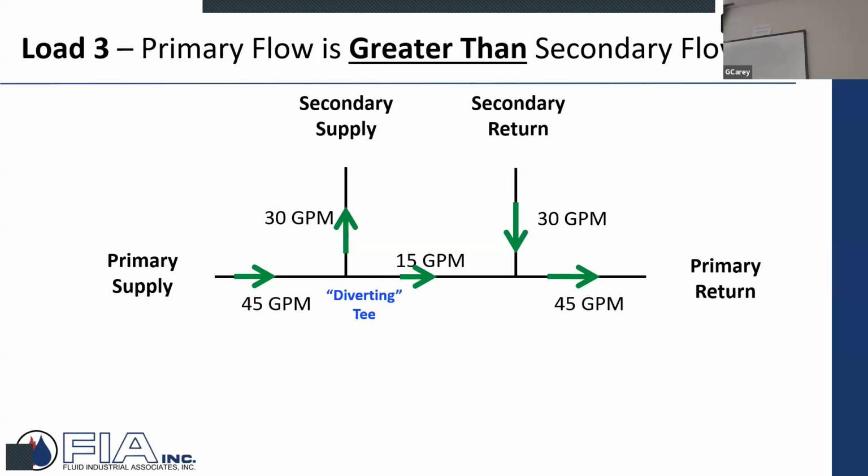So the fittings would have been just on the terminal units themselves. So once you get into the building, it was that main that would have a supply T and a monoflow T. That's your pressure drop. So as the water's going, pressure drop here, some of it diverts through that radiator back onto the main, but not going from building to building. That would just be inside each individual building, a two pipe system feeding and then a return coming back on the return.